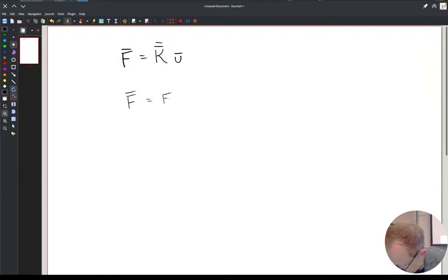But this is going to be E and A times, we'll call it K star, where E and A are both scalar values, Young's modulus and area, and then times that same U vector. So if area is 10 times bigger, then U is 10 times smaller. So that's one way that we could do this: because we're solving a linear finite element problem, all our answers are directly scalable.